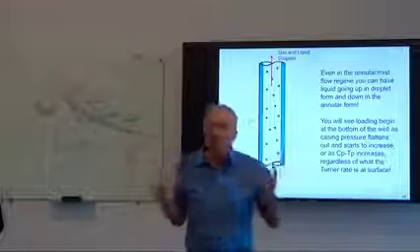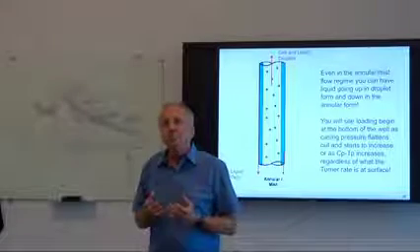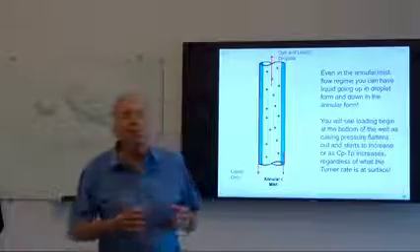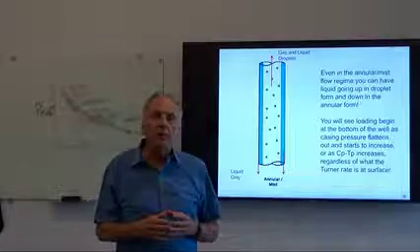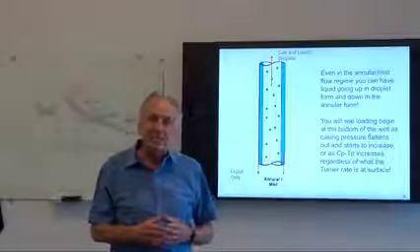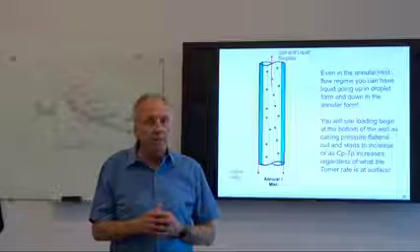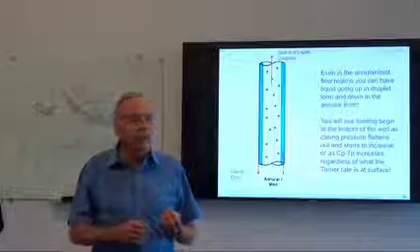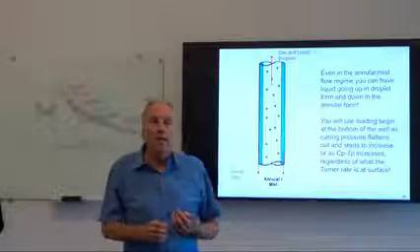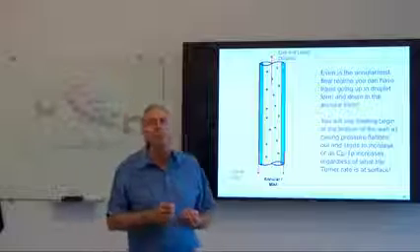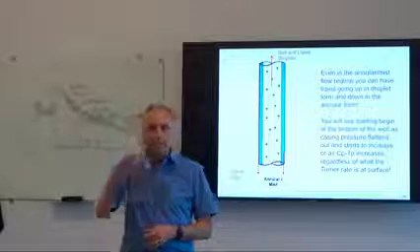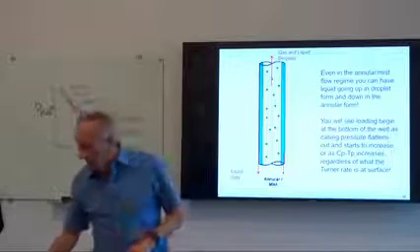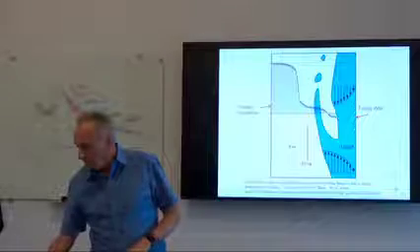We tend to think of that differential pressure as being representative only of amount of liquid in the tubing over that in the casing in static conditions, but in flowing conditions, it still is representative of the amount of liquid that is actually held up through the entire tubing string. It's something we need to pay attention to.